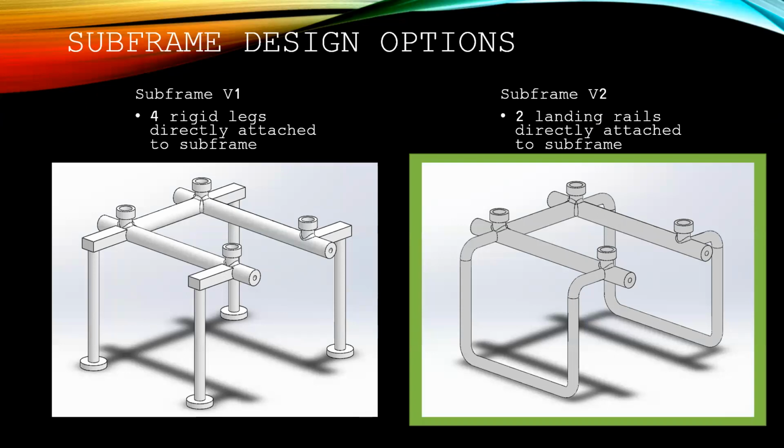When designing the subframe, our main goal was to reuse already existing mounting points rather than adding more mass into creating our own points. This drone has four circular Lego style connectors on the underside where we intended to connect the subframe to. In addition to this, we had to extend the landing legs out beyond the subframe to create a wider landing surface. This would produce a more stable landing process with regards to the drone tipping.